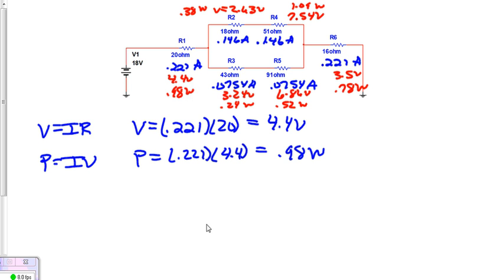Okay, and let's just quickly analyze the circuit and what happened here. Which resistor has the most watts? It looks to me the 1.09 here has the largest watts. Okay, and the smallest watts looks like to be the 0.24 watts right here. And that's kind of a good analysis of the circuit. And we can figure out if these were light bulbs, then we would try to figure out which one is burning the brightest. And just look at the watts to get the answer to that.